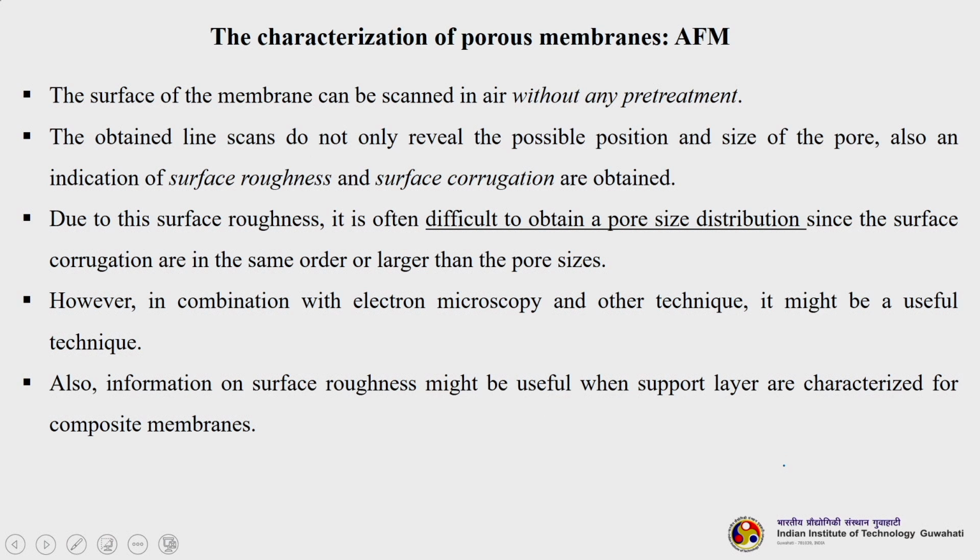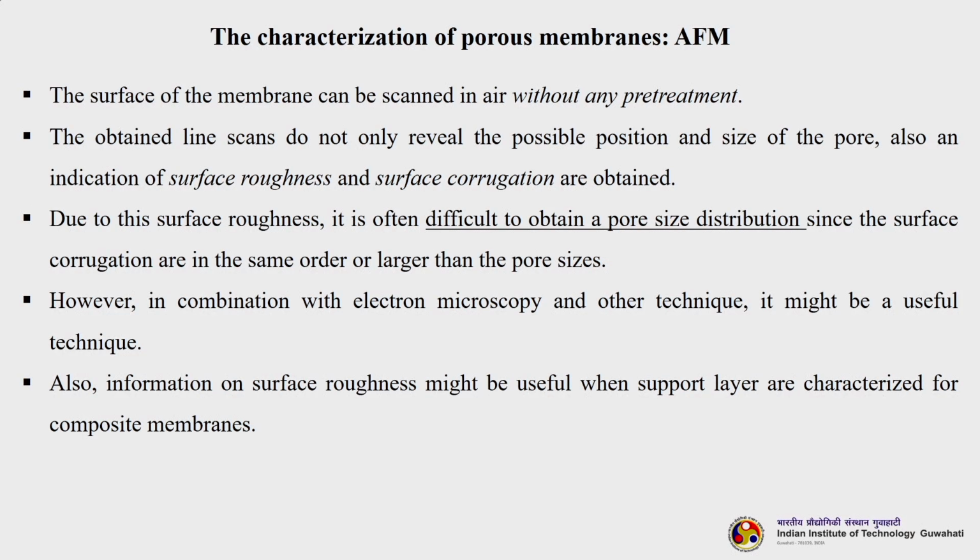The surface of the membrane can be scanned in air without any pretreatment. This is another advantage of the AFM. The obtained line scans do not really reveal the position and size of the pores, but also give an indication of surface roughness and surface corrugation. So, AFM is the only technique which gives us an indication of surface roughness. Due to this surface roughness, it is often difficult to obtain a pore size distribution. So, PSD or pore size distribution is a bit difficult to get in the case of AFM, which is very easy to do in the case of SEM.